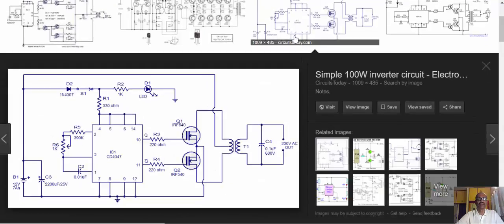This is a MOSFET circuit where we again have an R and C arrangement where we adjust the frequency, and we have the Q bar here which is directly feeding into the gate of the MOSFET. The biggest advantage of a MOSFET compared to the bipolar transistor is that you don't need current, you need just a voltage, so it can give that kind of voltage here to switch this on. And this is a half bridge arrangement where this MOSFET operates for half a cycle, and this MOSFET operates for the other half cycle, and that is how this is comparatively an acceptable circuit.